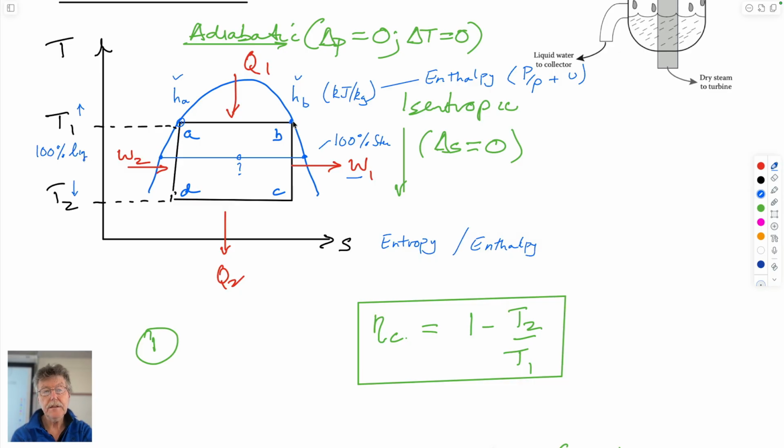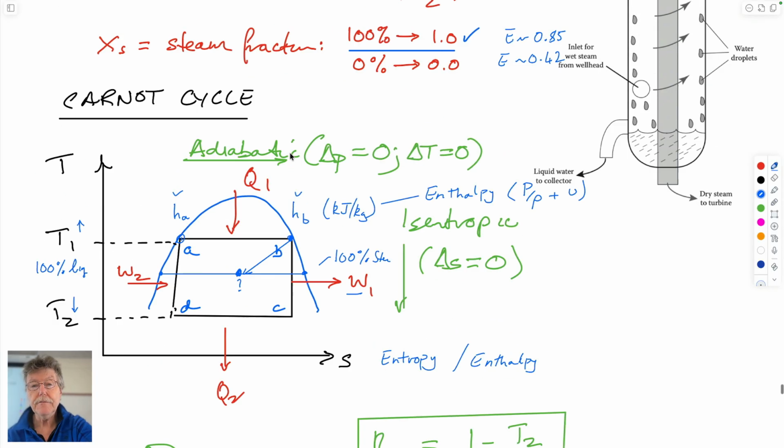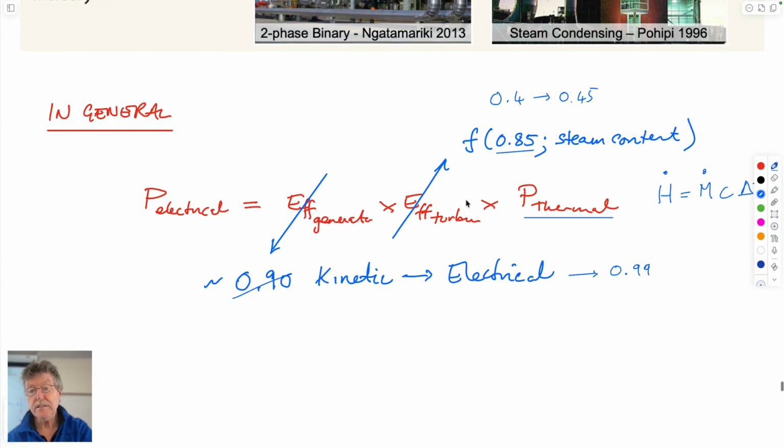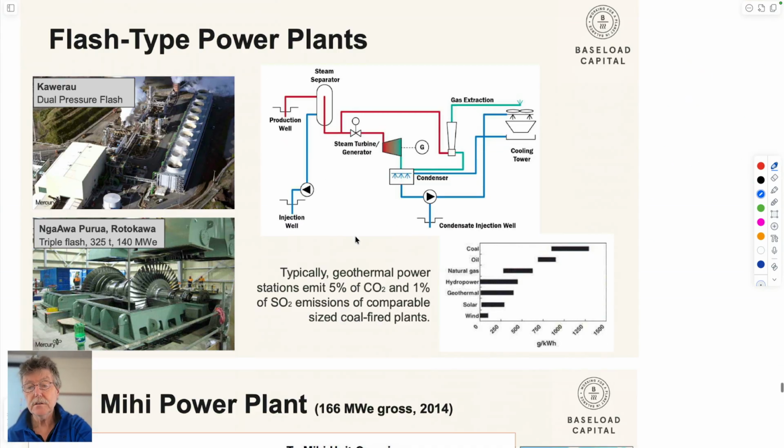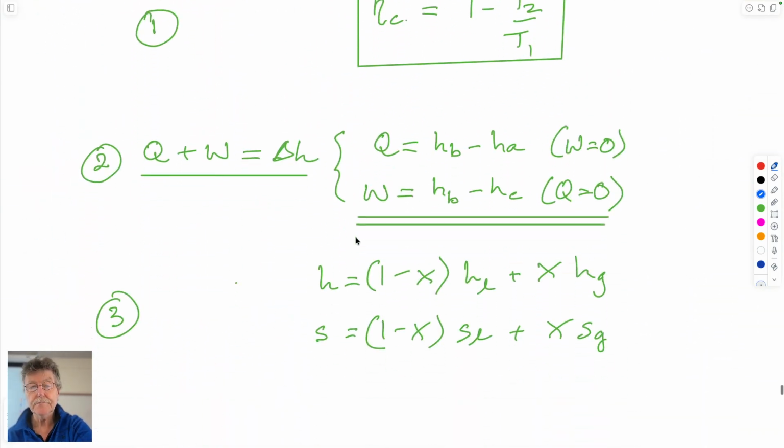And so in going from the inlet behavior to whatever the enthalpy is at this point, this is the trajectory that we take from inlet to recovery. So we can use that to calculate how much energy we'll get out of the water, which would be this amount of power we get out by flashing it. And then if we know what this power is and the two conversion efficiencies, we know how much electricity we'll get. It's always going to be less than the thermal power, because these are net losses, series losses.